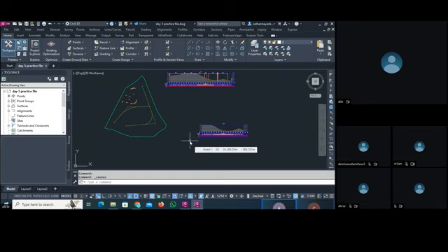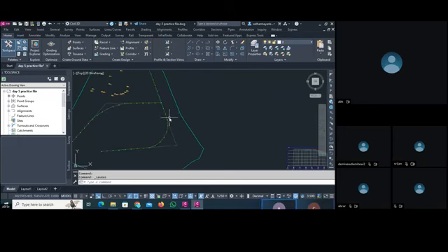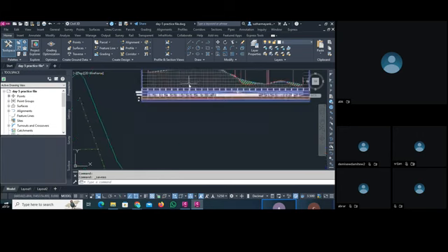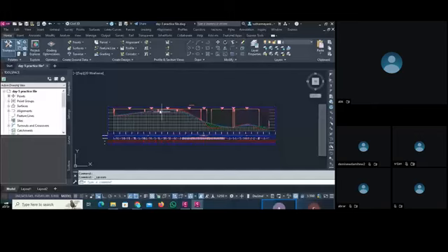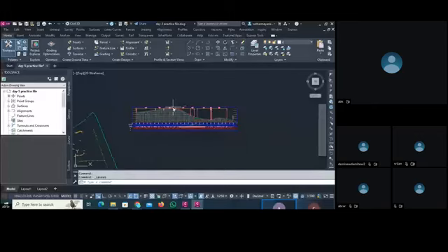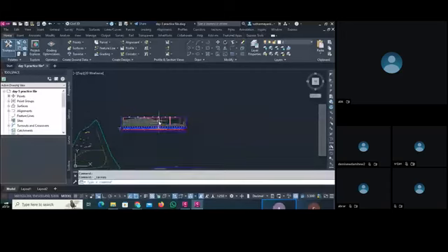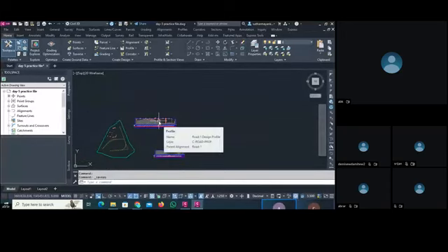So before we start the tool, first understand the complete workflow. You have to understand the total workflow in 8 different steps, what we are going to do today. The first is the alignment, horizontal design. As you saw here on the screen, we have drawn an alignment here. Then we create that vertical profile. This is a profile view and it is a vertical design of the road section. This road section and this road section. Okay. Then assembly, so road cross section design.